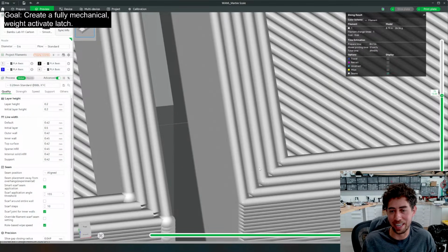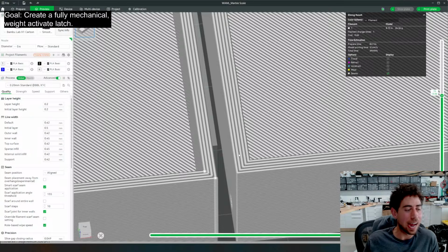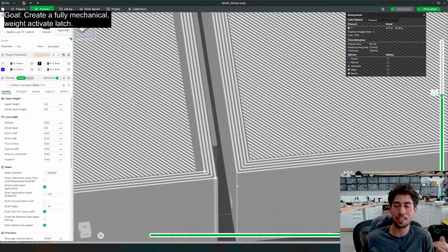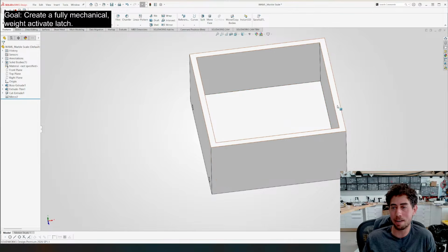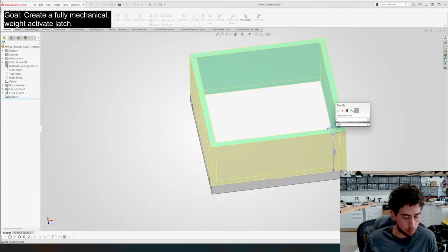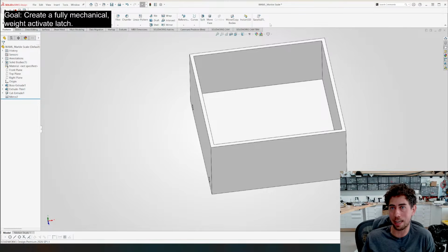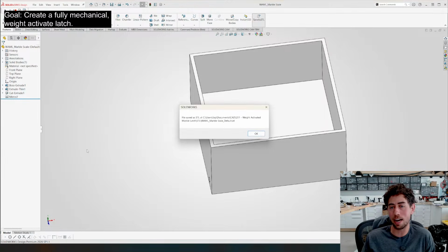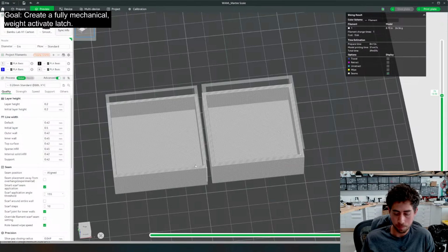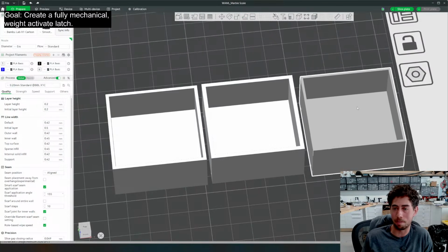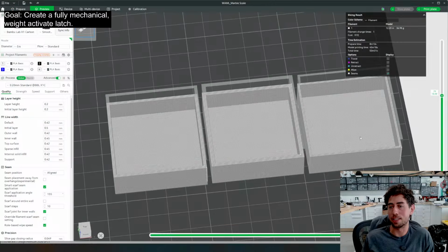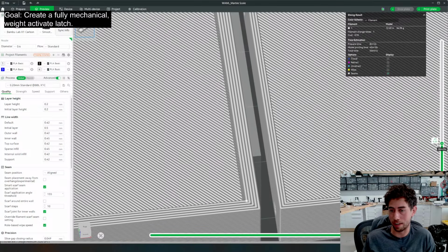So you get an extra layer line in there, which, you know what's funny actually? I have some old rules because the slicers used to be worse. This used to be a kind of crappy infill, but they've definitely improved on that. So you know what? I'm taking it back, but if that was 1.2, let's see what that gets us. I think that gets us 3 lines for thickness, and that honestly might be fine too. But this is one of the things that determines some of my dimension choices. So that gets you 3 layer lines. And those are nice.